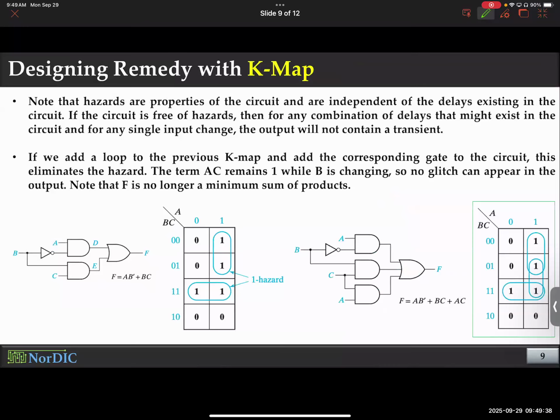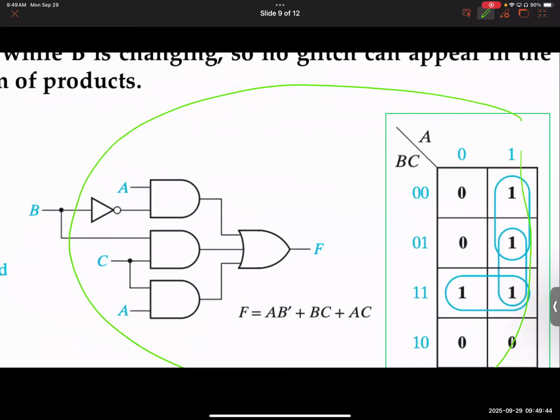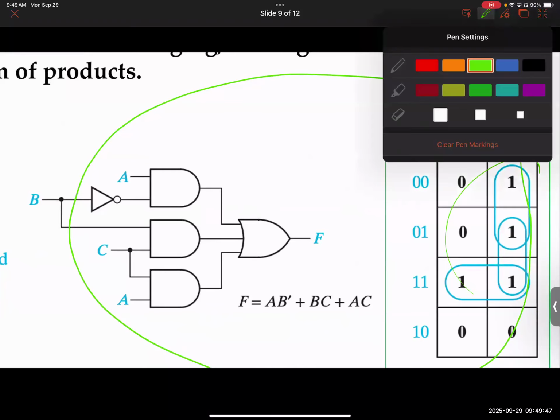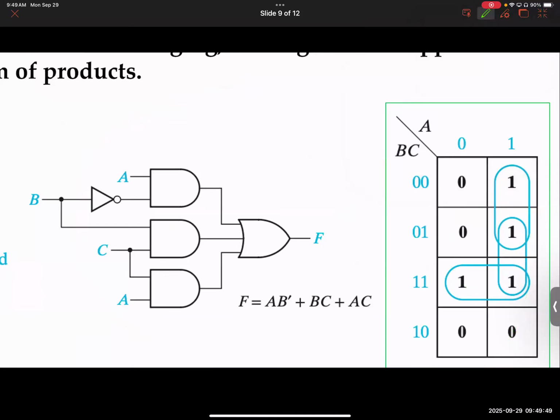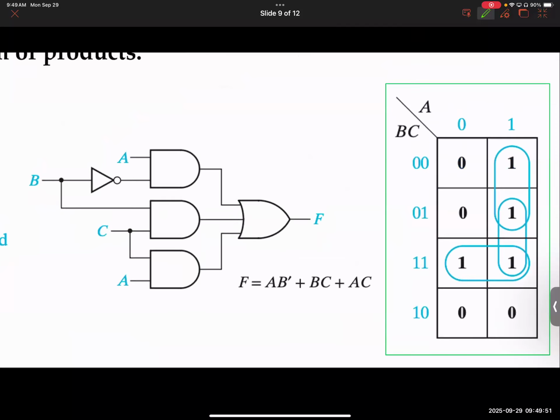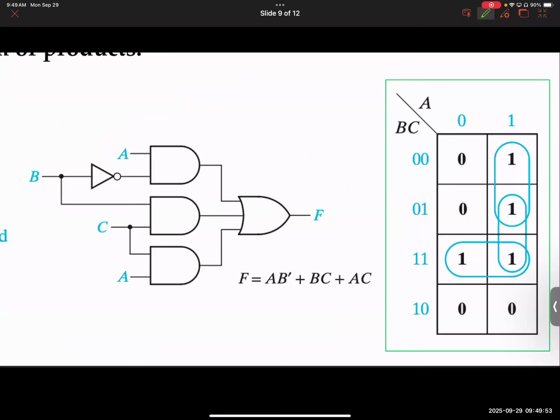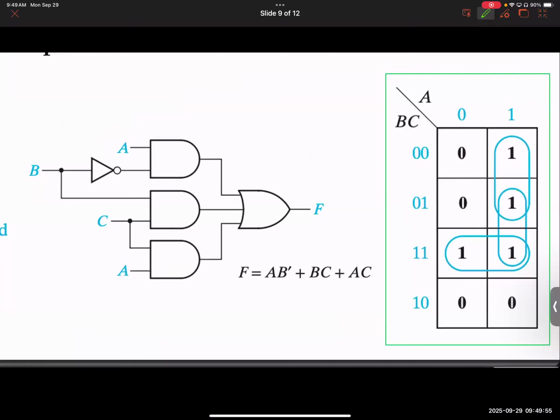Let's get to the next. This is essentially exactly what we saw before in the previous slide, and this is the new slide. Can anybody tell me what changed here in this K-map? This should be the exact same system, but something changed here. Yes, I chose to use an extra group. Can I do that without changing the logical outcome, folks? Did I tell you that?